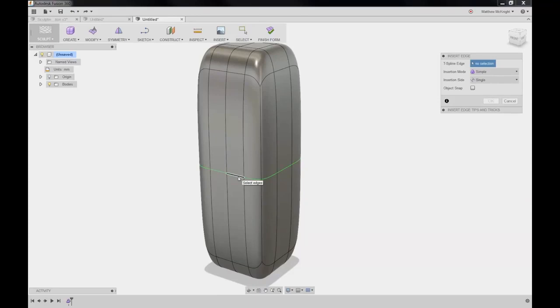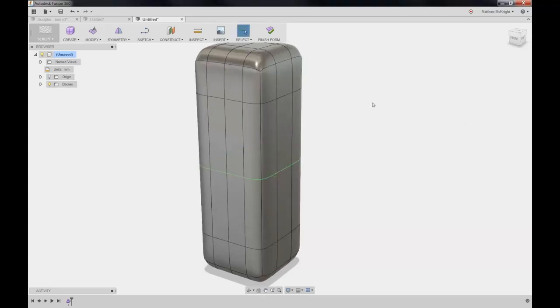So the way that you can group select is by double clicking. So if I double click an edge, it will group select all linked edges. So in that case, it's group selected all of the edges around the outside of our part. And you can see here that we can then manipulate this geometry and add some additional edges and faces in place. The good thing here is then we can add effectively a whole bulk of features and faces inside this area.